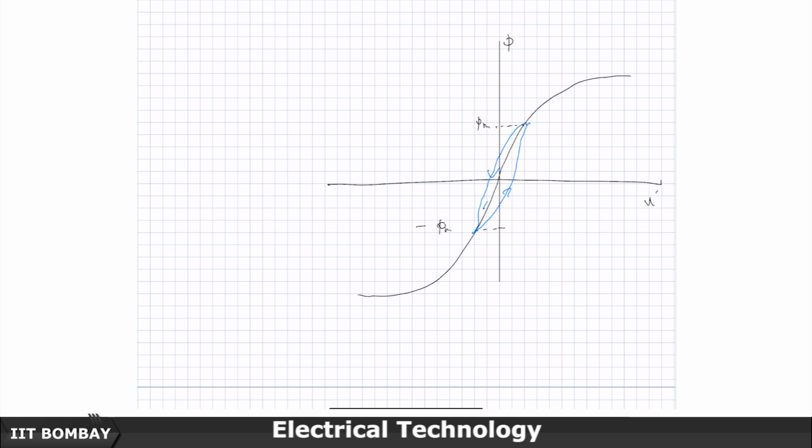So, because of this, normally when we write the equation of a plain inductor, we will write it as V = L dI/dt, and if we want to write a phasor equivalent, we will use the Heaviside operator, write p equal to j omega, and write the phasor equation as V = j omega L I phasor, which is to say that V leads I by 90 degrees, or I lags V by 90 degrees.